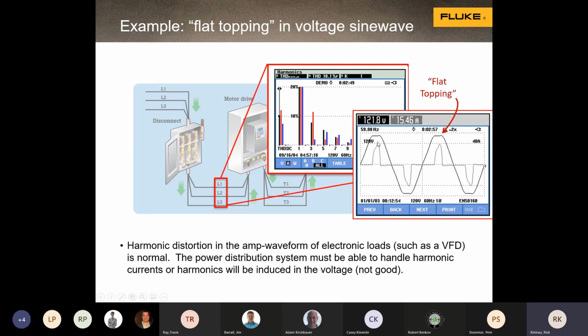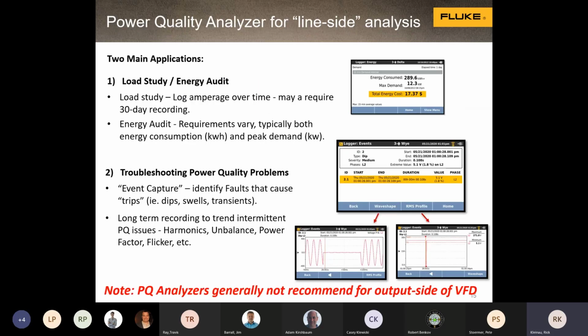The drives were running fine, didn't hurt anything, but remember, it's this peak voltage that generates the DC bus. So you can have what looks like and measures like, with a regular meter, pretty good voltage. But if you don't have enough on the peak here to run the DC bus or the computer at whatever voltage level it needs, then you've got trouble. Well, just a little note.